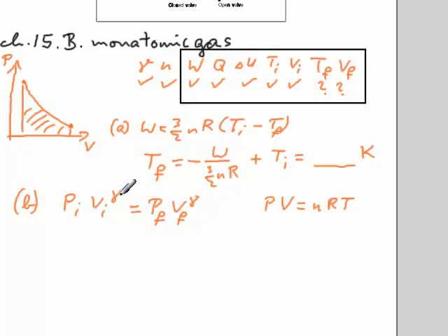But what that exponent does is it gets rid of the temperature, which during an adiabatic process changes, and in getting rid of it, it introduces that adiabatic index. So this one here is kind of an abbreviation for the ideal gas law having kicked out the temperature. It only says pressure and volume, and keep in mind the temperature does change, and the exponent gamma is substituted instead for that.